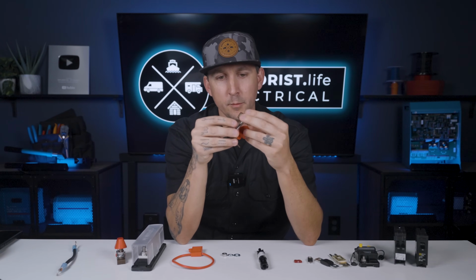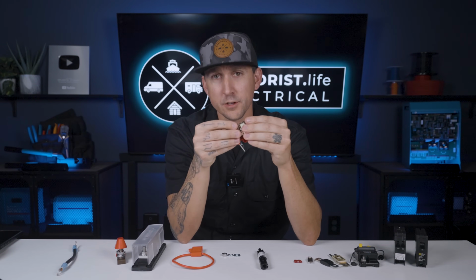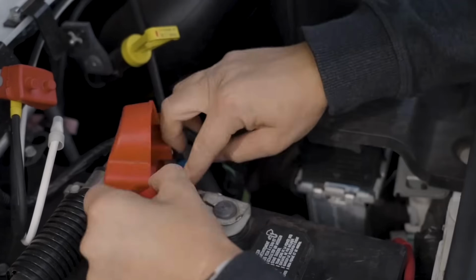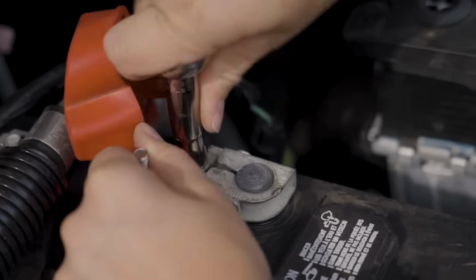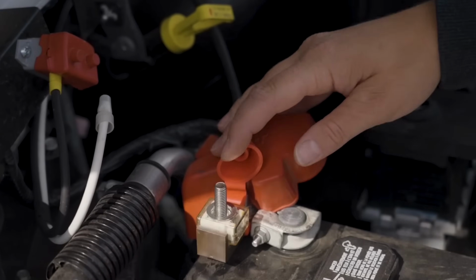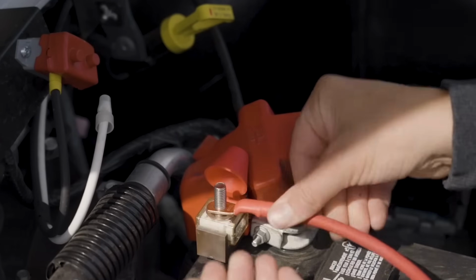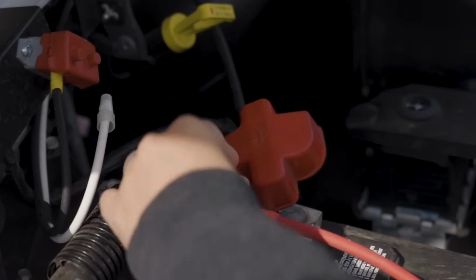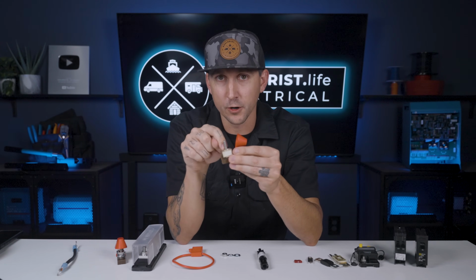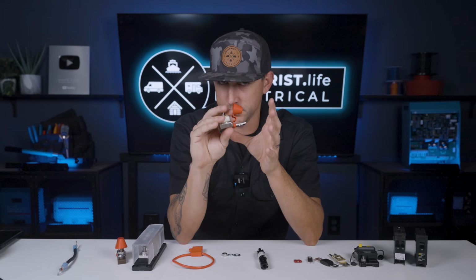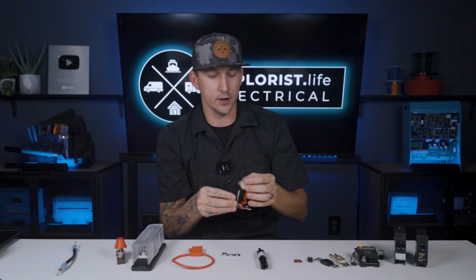We use this one a lot in conjunction with the MRBF fuse holder. We'll talk about the fuse holders later, but we use this combo a lot for alternator charging. This works really well for attaching to the top of a factory starter battery in pretty much every vehicle, every truck, every van, et cetera, and it protects the wire coming from the starter battery to a DC to DC charger. That's where we most typically use this one here.